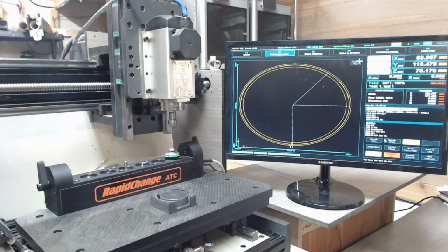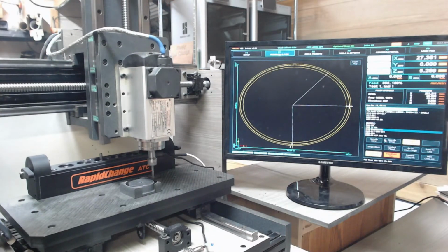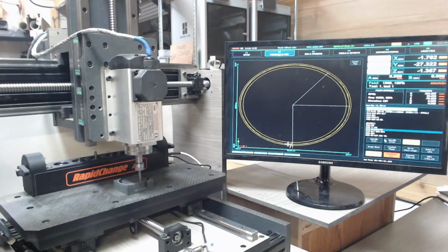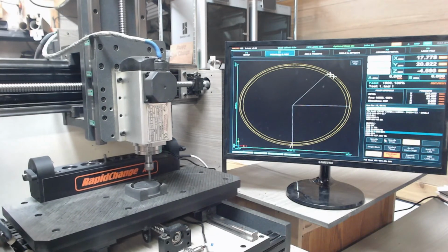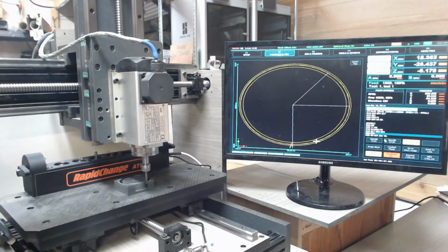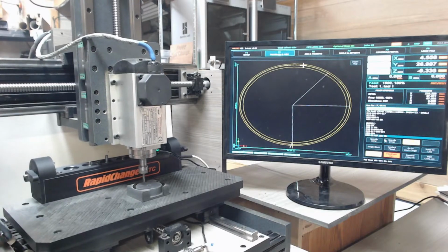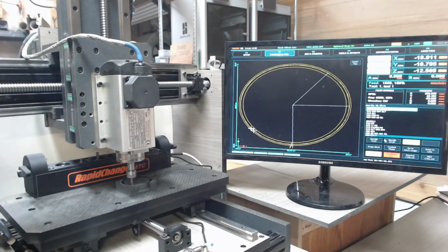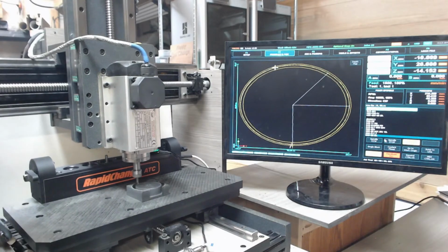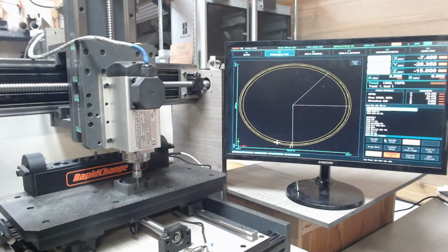So my good friend and field tester Guillaume Furlan came and we worked on it this weekend and got the IR sensors working, and then we got a little tip from Masso support on how to set up the linear tool changer to avoid having to do the cycle start every tool change. It's just super sweet.